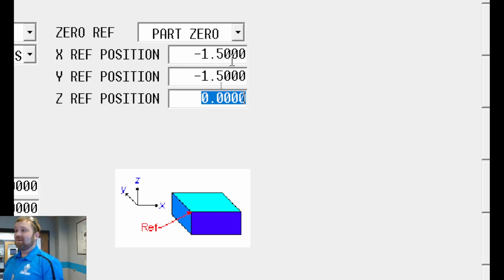Or like Mastercam, the work offsets in Mastercam, because G54 is work offset number 1 by our book, by our list, by everything else. But in Mastercam, when you pick your work offset, you put a 0 if you want work offset 1. Because the way Mastercam works is it takes the number you put in the field, and G54 is your first one, and whatever number you put in the field, it adds to the 54. So if you put a 0, 54 plus 0 is still 54. You put 1, you get your 55, 2, and so on. So, just one of those things that we just have to get used to.